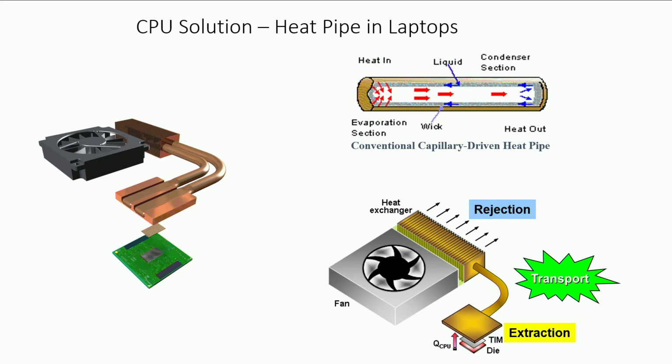We can do a lot of analysis, which I am not going to do here, but it can be shown that the pumping action, the pressure head that the capillary action gives, is balancing the flow resistance due to flow of the liquid through this porous medium. People who are familiar with porous media know there is something called Darcy's law, mu u over k. It is also overcoming the frictional pressure drop because of the flow of the vapor through the annular core. Darcy-Weisbach formula, friction factor. Even if you do not know it, not a big deal.